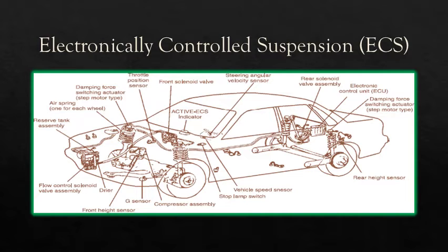Nose dive under braking is not only uncomfortable, it is dangerous. In an accident, a car which has nose dived severely is likely to go underneath the car in front, and the impact would be taken by the car's windscreen. By monitoring vehicle speed, longitudinal G-force and brake pedal application, the processor knows that the car is braking and not just going down a hill. It adjusts the ride height of the front of the car to maintain a level ride.